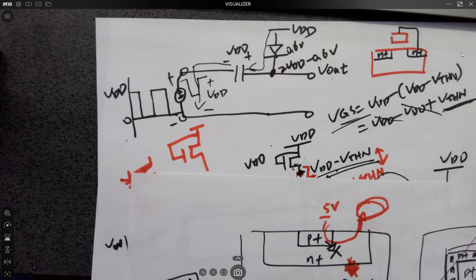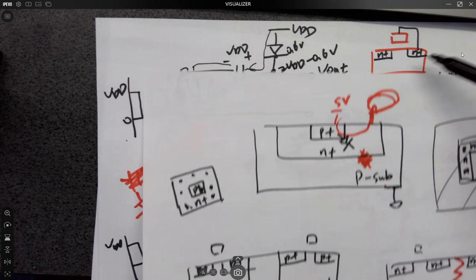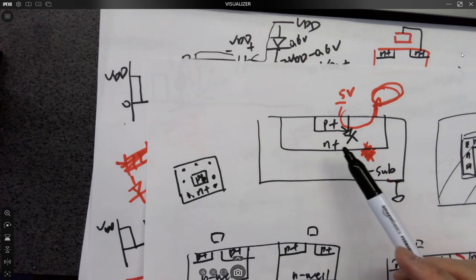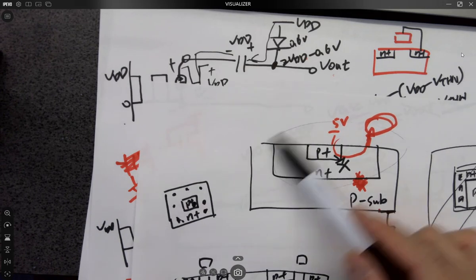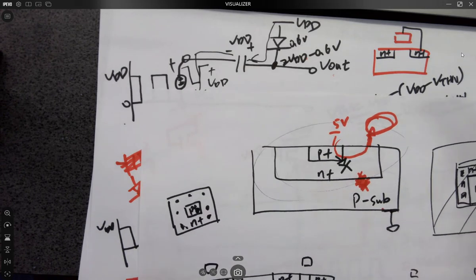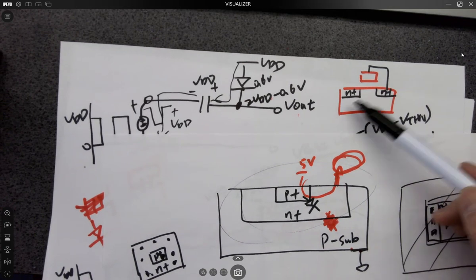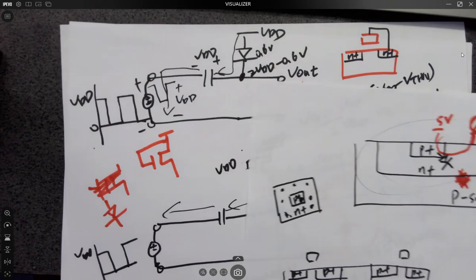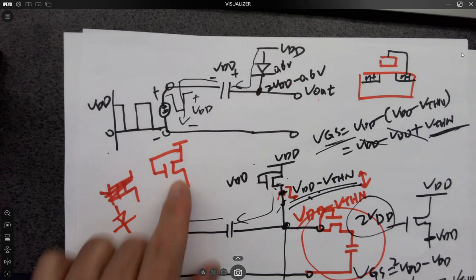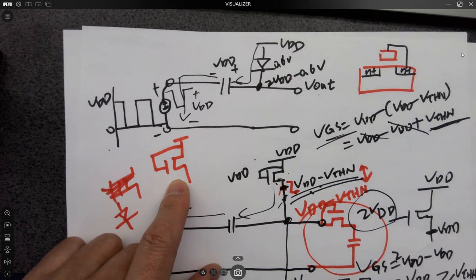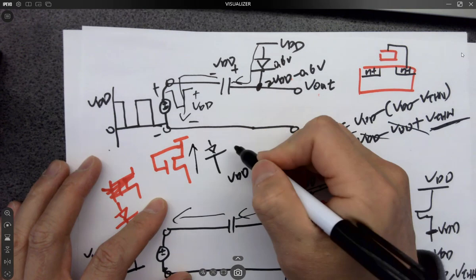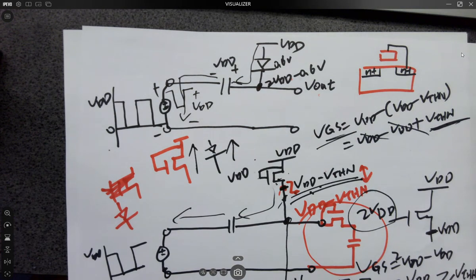All right, so you can see these are different, right? For the layout, the cross-sectional view, the P-N junction looks like this. It's a very simple diode. And the NMOS is still NMOS, right? It has P plus and all the channels. So the point here is, if you connect your transistor this way, it performs as a diode. The reason for that is the current is not going backwards, similar to the diode.